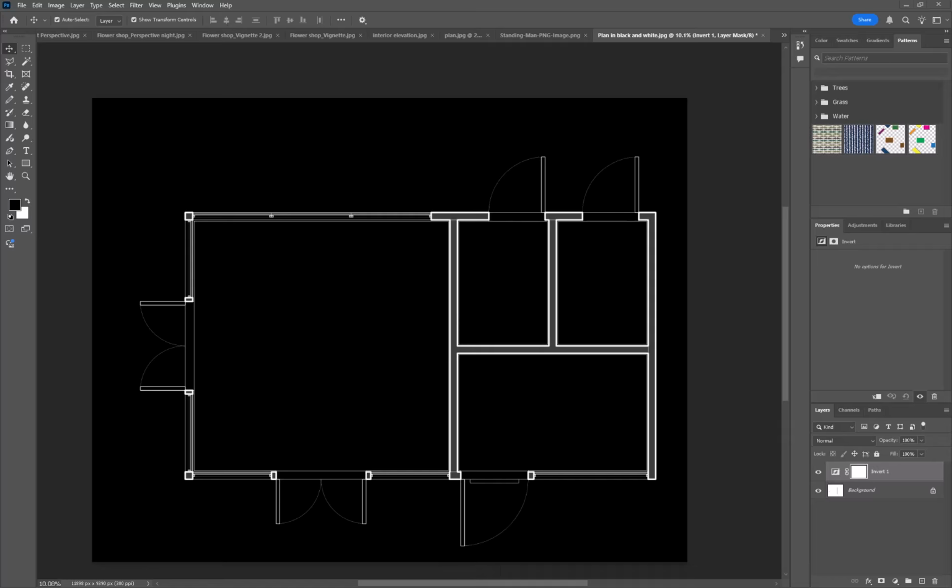So you have gone through, opened every single one of your images, the 10 architectural drawings and the 4 images of materials for your project. Again, you can have more images, you can have more materials, that's okay. But open every one, check the image size using Photoshop. Use your cropping feature to get rid of the Lumion logo and add in any other features that you think would look nice. Poché, additional scale figures, even just some extra lines to make those elevations look sharp. I guess there's only one exterior and one interior elevation. But anyway, there you go.